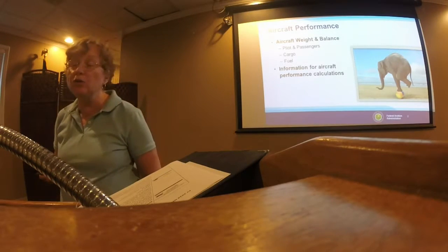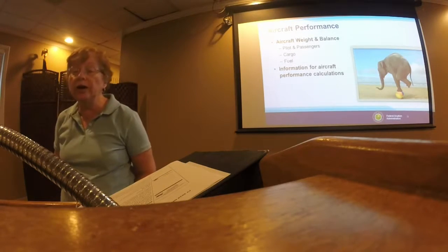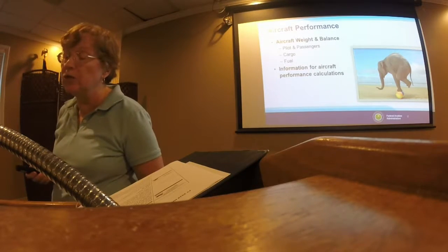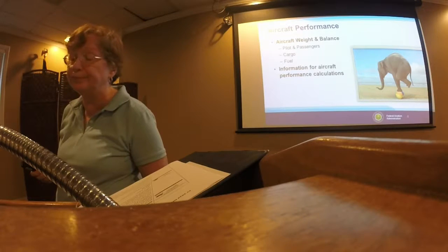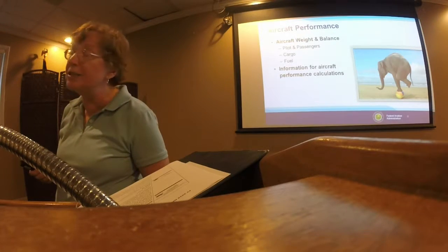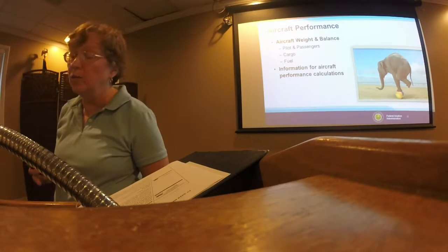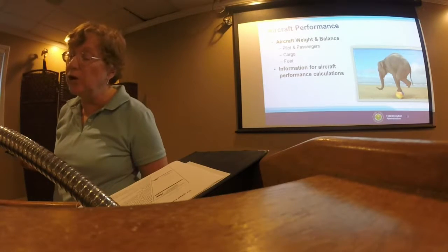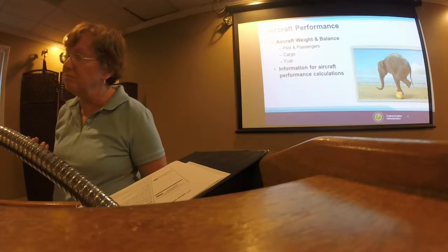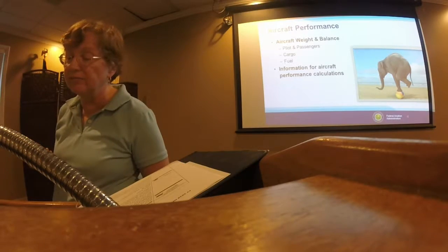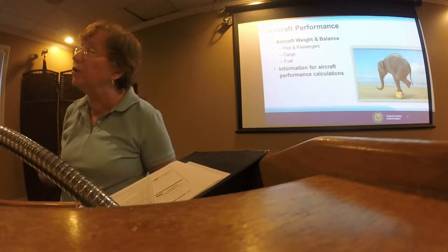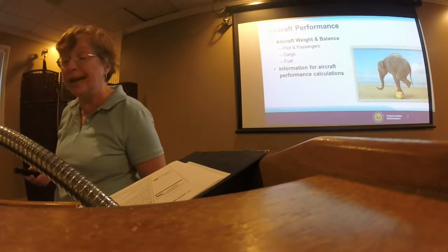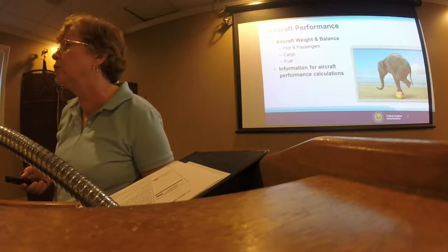Once you know how much you want to haul, you can figure out how much fuel you can take, and that together with your weather information will tell you how far you can go. If you have enough to get to the destination, plus an alternate destination, plus a reserve, then you're probably okay. If not, you'll have to figure out where you're going to stop en route and how much that is going to add to the time frame as well.